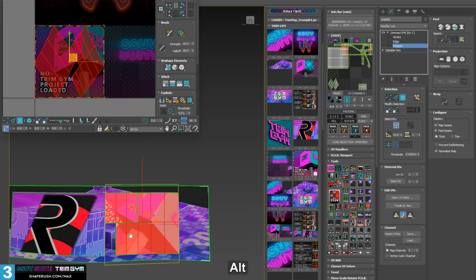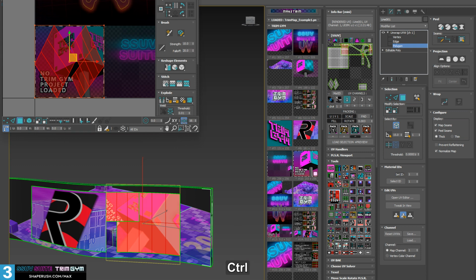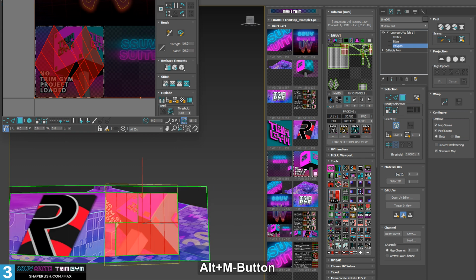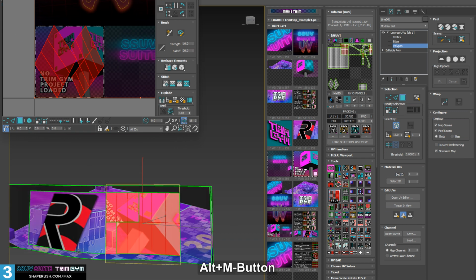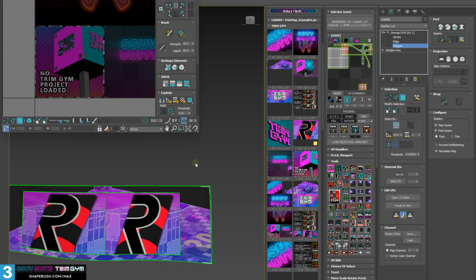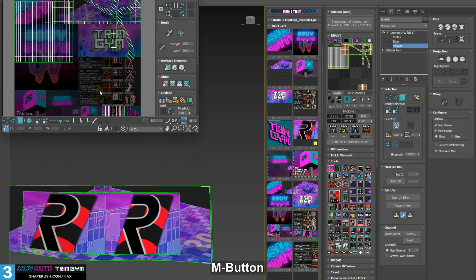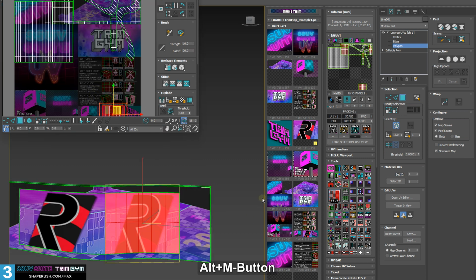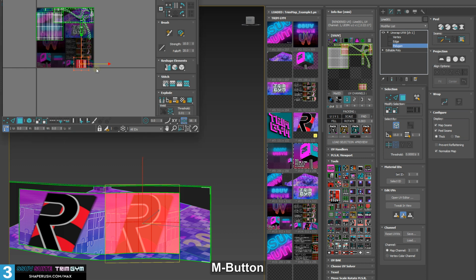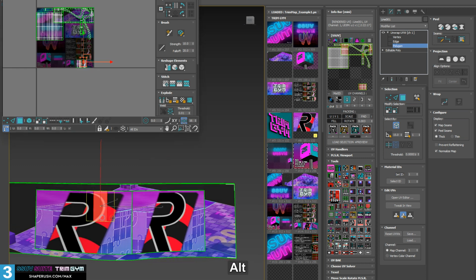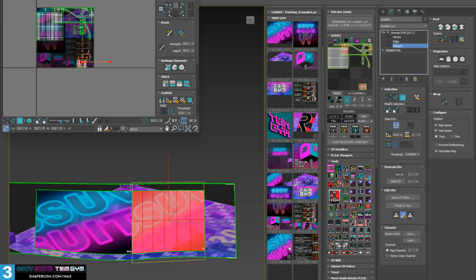And if we didn't want that to happen, if we wanted to actually heal this, we can select this. Now I'm going to shift and right click. And what this will do is planar map what we have. More or less, it's going to break these out, heal these, and essentially give it an average planar map. But it's also going to conform it to that space that we defined in the trim piece. Okay, so left click will iterate through these pieces like so.